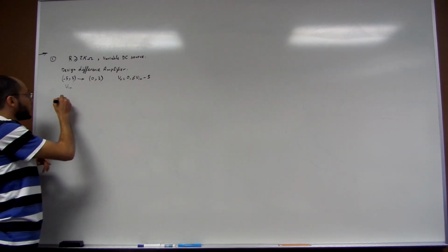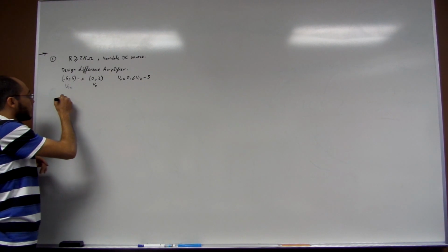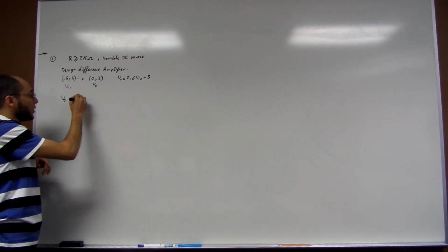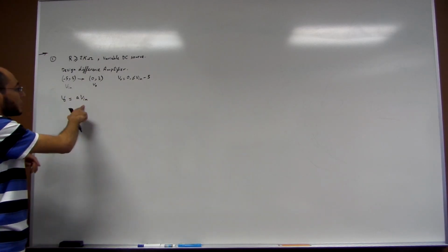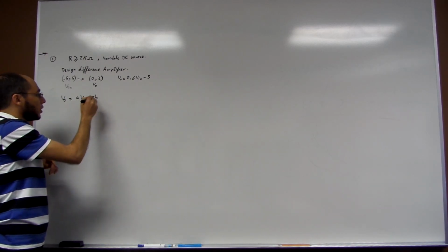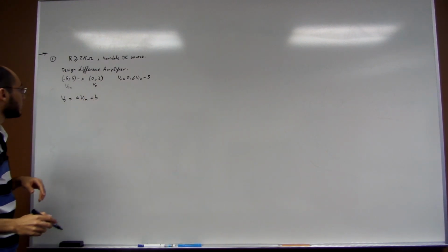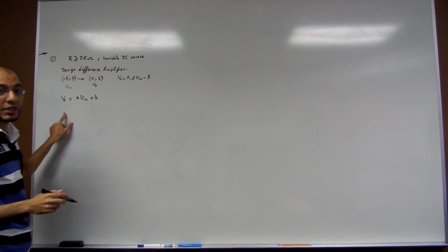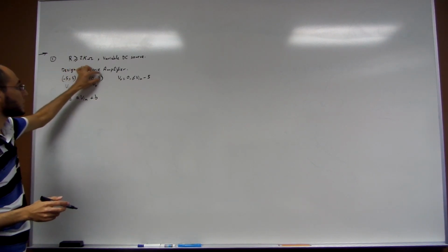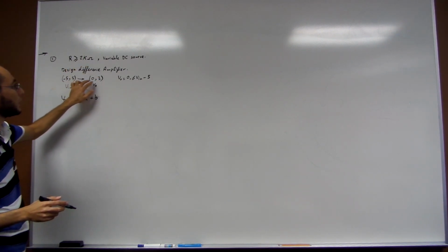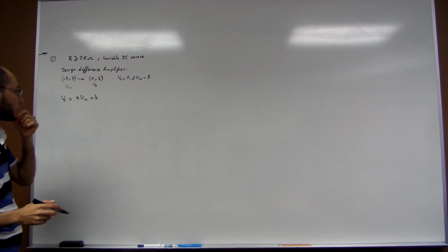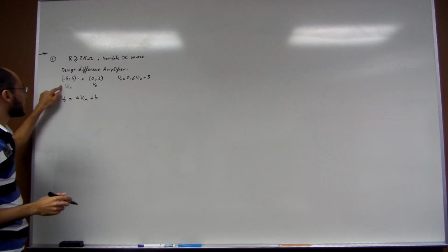Which means that what you need, so that's the output and that's the input, is to design something that produces an output given the input. And the output is nothing but a scaled version of the input. So what are the values of A and B that do this conversion, from -5 to 5 converting to 0 to 3? That's the question I want to answer.